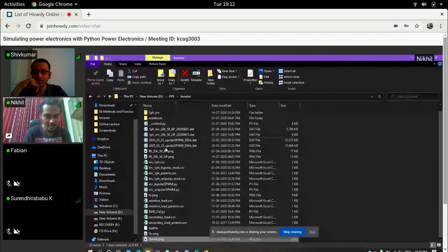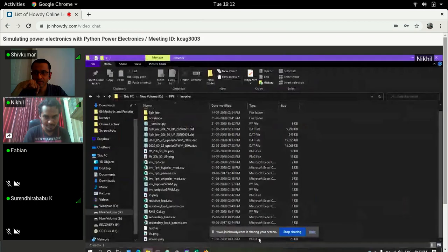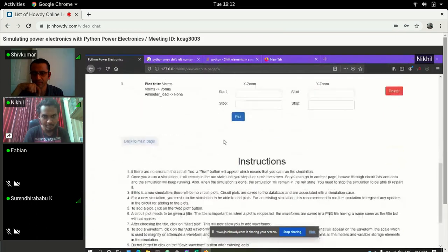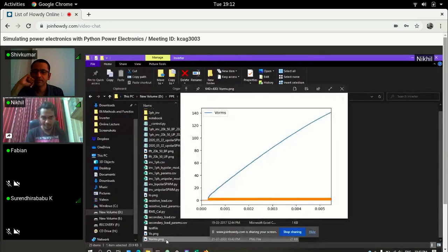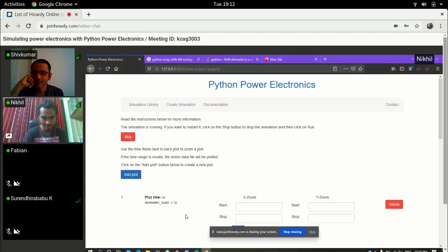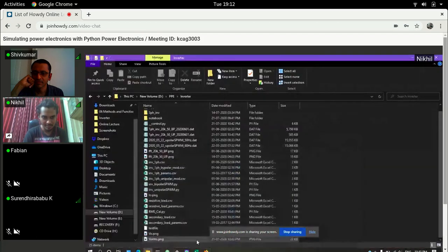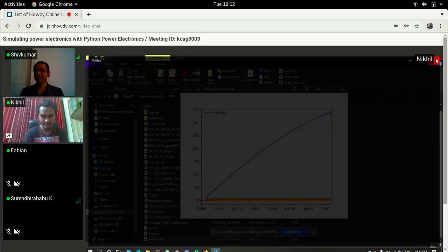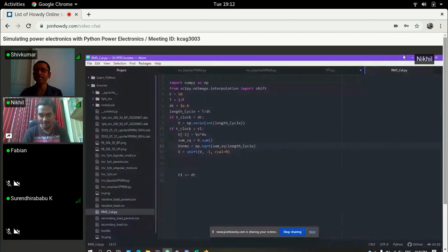You come down and plot. No, you have to plot, you have not plotted. You need to click on the plot button. It won't work without that. You plotted? I didn't see. Yeah, I plotted. I see, okay. It was fast. Yeah, so it's increasing, it will settle to whatever, 240 volts or something. Yes. Yeah, it's reaching there. It will just take a little more time, but it's done. So this is how you calculate RMS. And it will be a steady value after that unless the voltage changes.